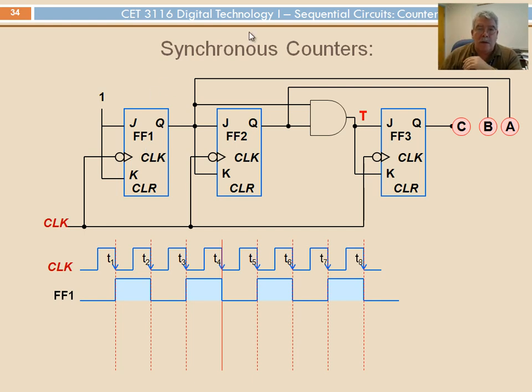So this is not that difficult to follow. In this case, that's what we have in the first example of synchronous counters, which we tie. But for the third, I need to be sure that we only change when these 2 reach 1 and 1, and they stay there until the next time these 2 reach 1 and 1.